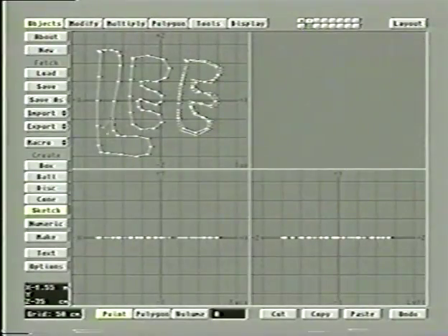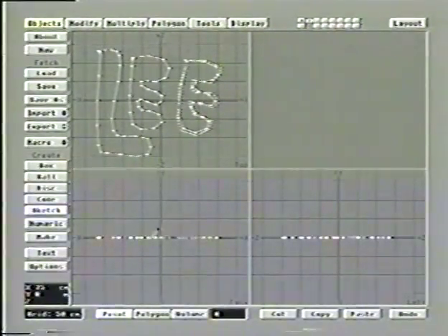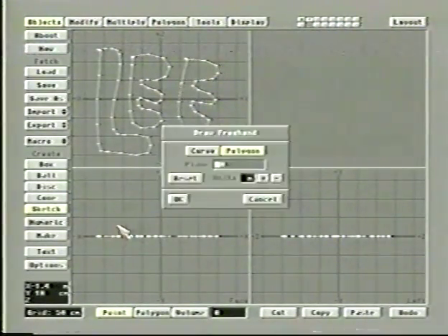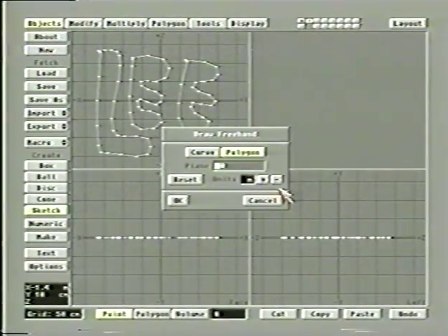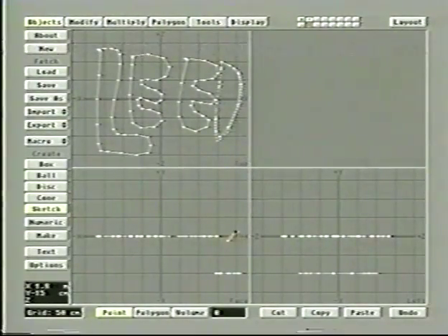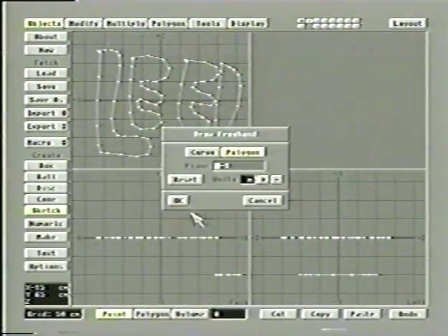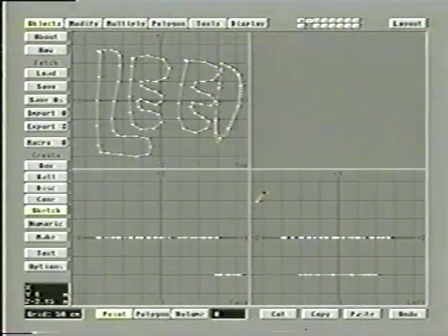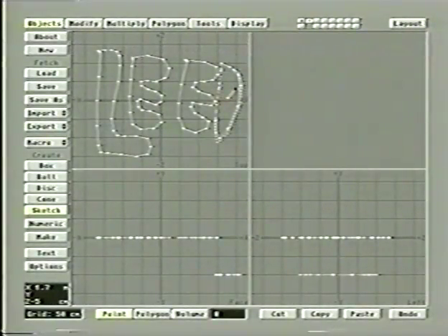The one other option you have in the numeric one shows you which plane you're moving it in. In other words, you're drawing this, let's say, from the top view here. Well, it automatically puts it at 0. If, on the other hand, I go to the numeric option, I can choose another plane, such as -1. And what this means is the next thing that I draw here, you see it's drawn at -1 meters, because that's what we had selected here, 1 meter for our units. So it drew it at a plane of -1 meter this way. In other words, since we're drawing on the front face, it knows to draw it normally there, but it's got to figure out where to position it, and you can select that numerically.